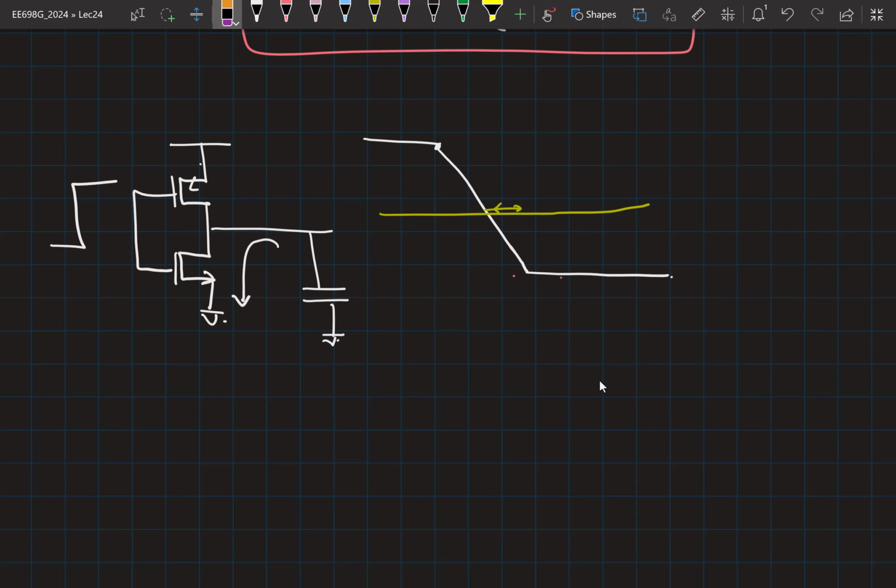Okay. So let me bring out the point I wanted to bring out. During this period, when the NMOS is completely off and PMOS was on, PMOS is basically in linear region, acting like a resistor. So it will have its own thermal noise and flicker noise even during that period. Because of that, the value here is going to fluctuate.